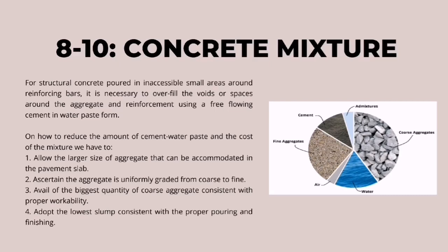On the contrary, in pavement where the slab is open and thin with access to manipulate from the surface, a drier mixture can be poured inside the form with ease and success. Thus, a higher percentage of aggregate and less fluid cement water paste can be used.